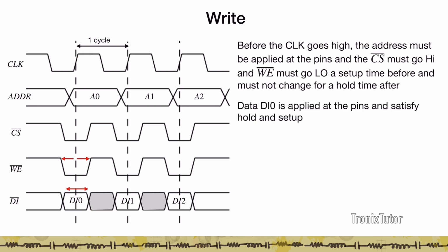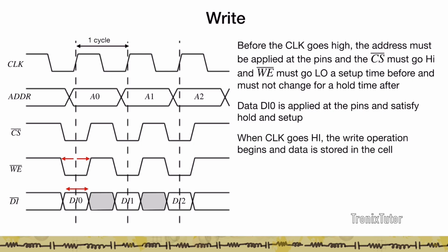And once the data is applied to the pins and it satisfies the hold and setup at that point, then data gets written into the memory. So when the clock goes high, the write operation begins and data is stored in the cell.